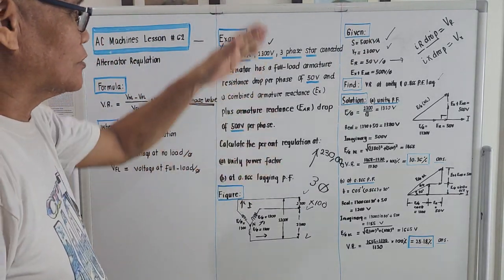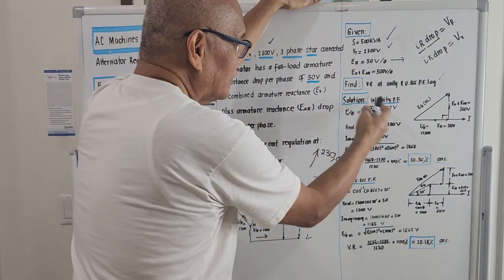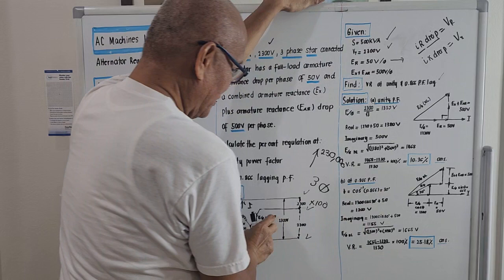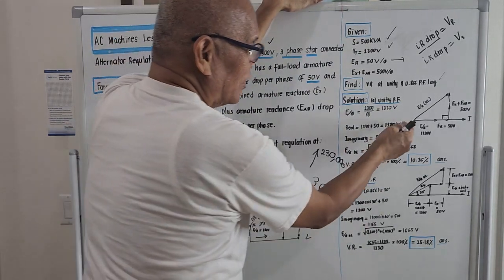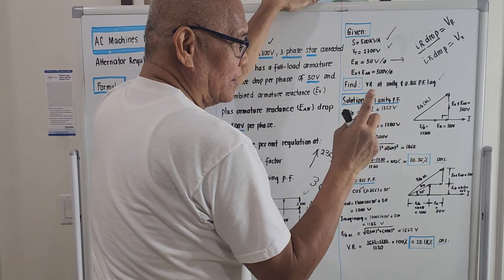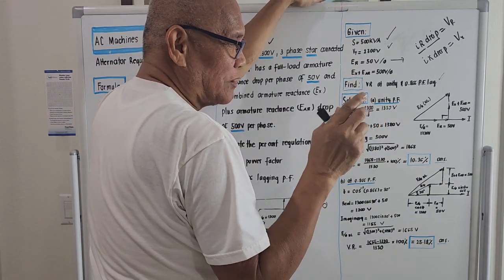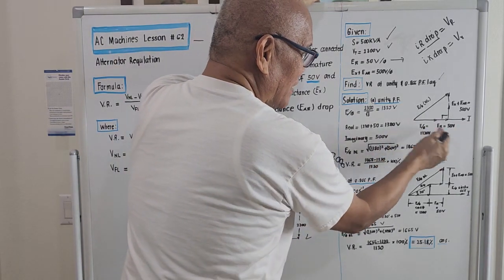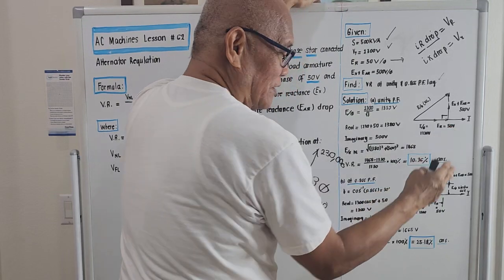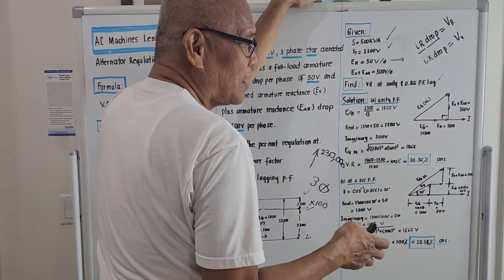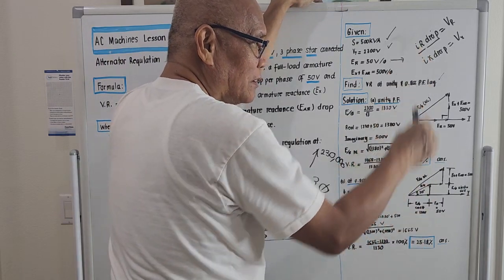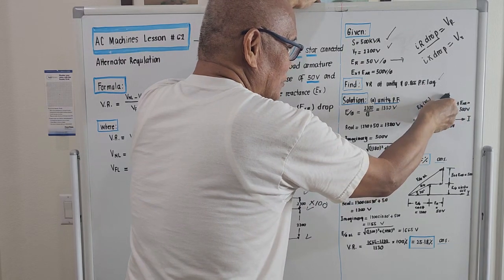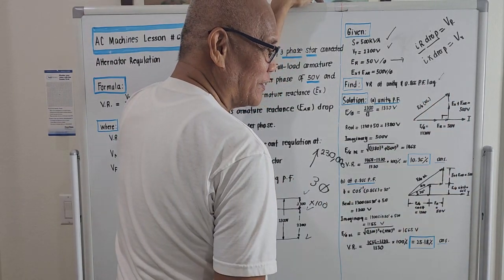Okay, let's try to bring out the solution. If the power factor is unity, this should be the vector diagram. This is the current. This is the voltage per phase on the alternator winding. They are in phase. And the drop due to the armature resistance is in phase with the phase voltage. This is a real part voltage. And the imaginary part voltage, the reactance drop, is actually erected vertically. So this is horizontal, this is vertical, this is hypotenuse. We are on the study of trigonometry.